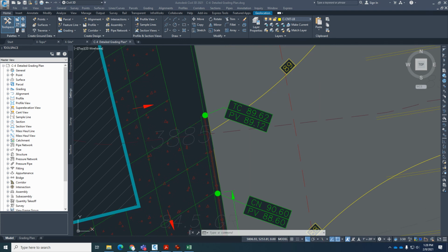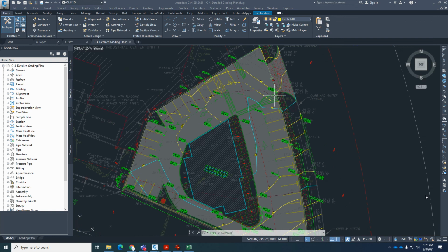Okay. And why are we doing that? Why don't we just leave it at 85? Well, the thing is that we got a building, and the building elevation that the engineer decided to use is 90.83. The elevations over here on this road is about 92. Way down here, it's about 83. So this road is actually dropping in elevation quite a bit.